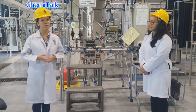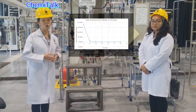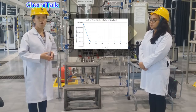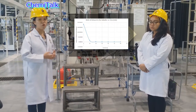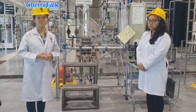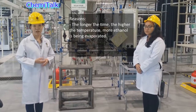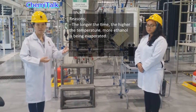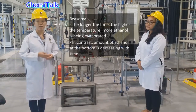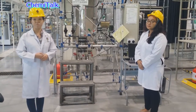Yes, we also calculate the moles of ethanol left in the reboiler, and a graph of moles of ethanol against time is being constructed. From the graph, we can conclude that the moles of ethanol in the reboiler is decreasing as time is increasing. This is because when the temperature is increasing along with time, more ethanol will be evaporated and collected at the top of the distillation column as distillate. In contrast, the mole fraction of the bottom products will be decreasing with time.